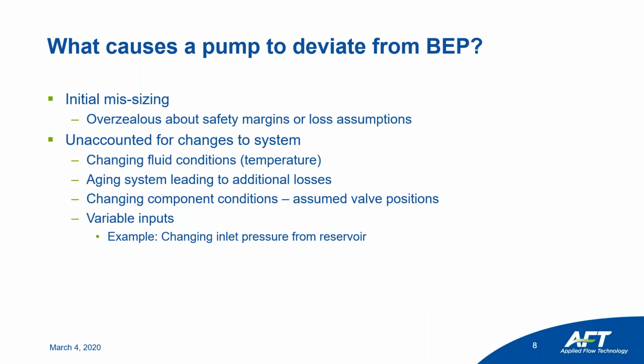Another thing to consider is if your system's getting older, so your components could start breaking down, though that's kind of unlikely. You could see potential issues like scaling on your piping, where you're closing up that internal diameter, and roughness could also gradually increase depending on the circumstance.